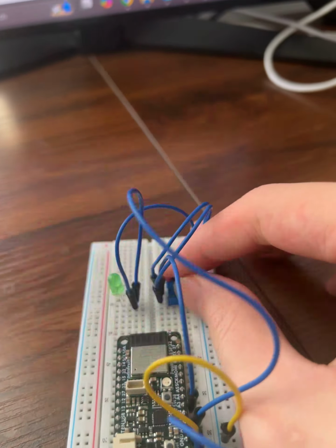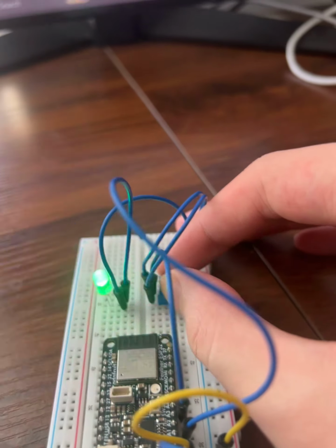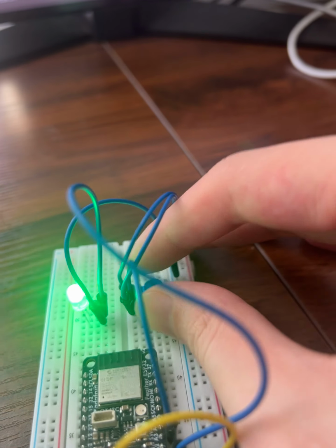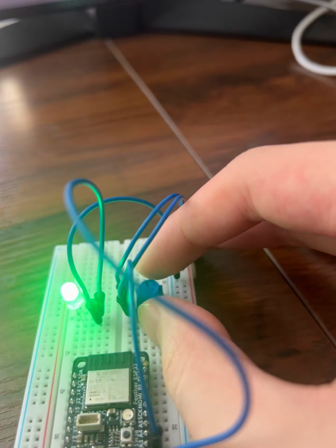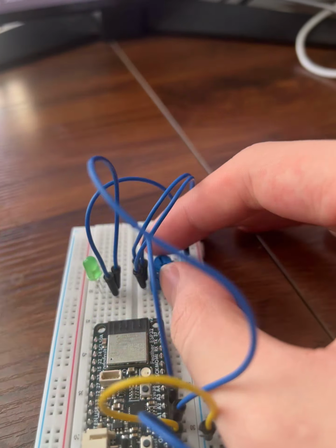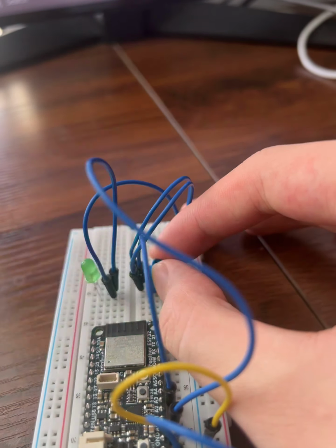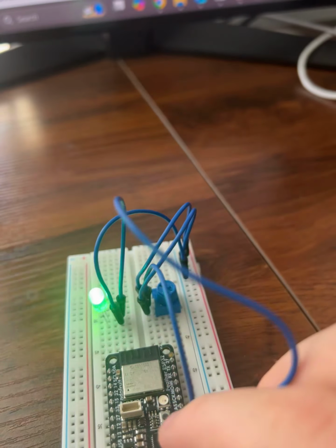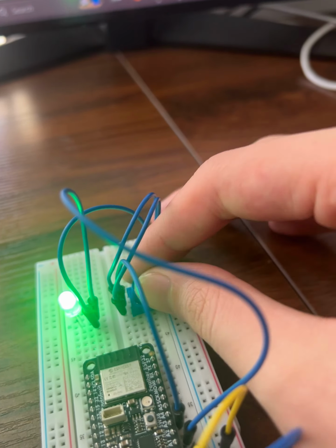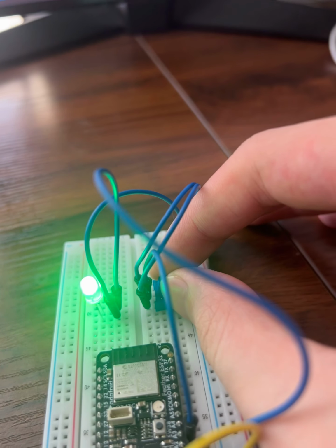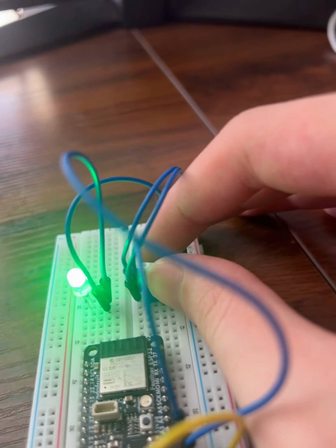But if I click the push button for the first time, now I should be able to toggle the frequency of the LED. So if I twist the potentiometer clockwise, it will blink slower, and vice versa. If I press the button for another time, I'm now setting the duty cycle of the LED, which you can see. Well, now it's because it's too bright so that you cannot see it blinking.